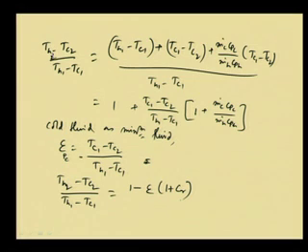Cr is the heat capacity ratio, and this is the effectiveness, which is equal to, the right hand side of that expression had been exponential minus UA by Cc into 1 plus Cr. That is what was this case.